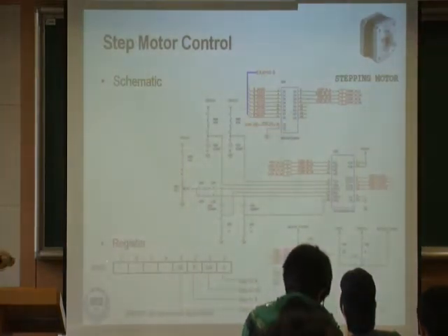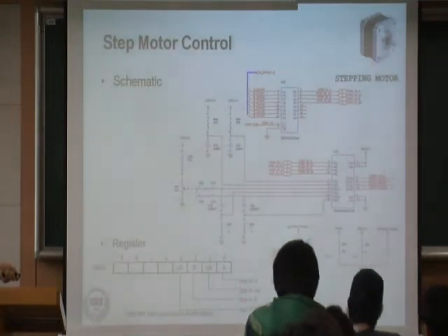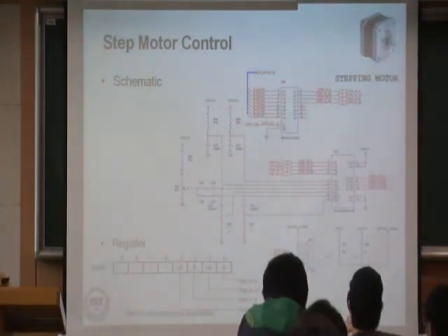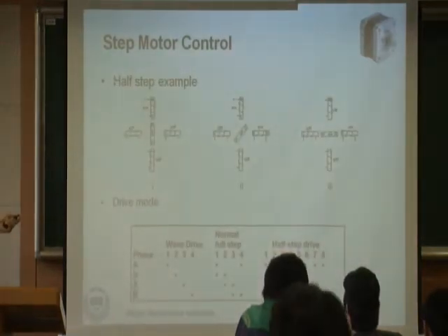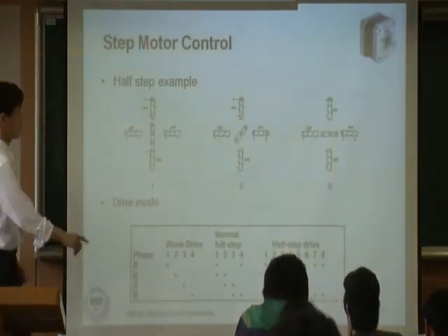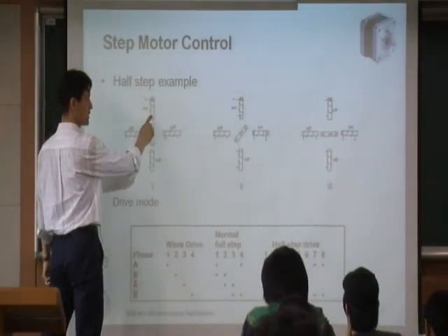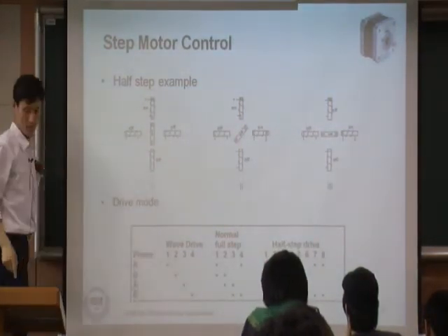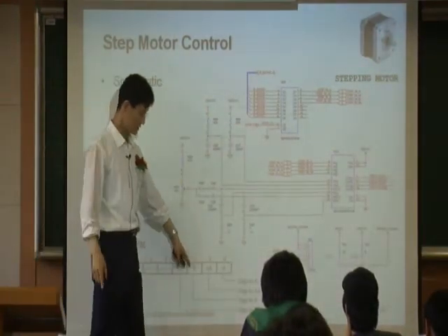Each step motor may have a register like this, step in A, B, and this basically tells you what to enable and what to disable. In this case, we have 4 magnets, so each one has one bit. Like this, for example, right? We have 4 bits like this.